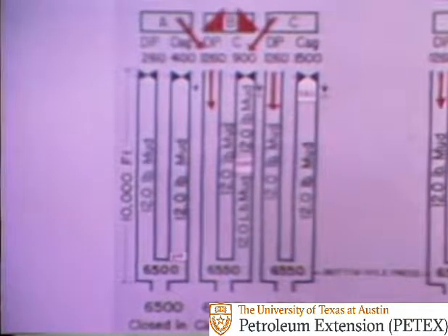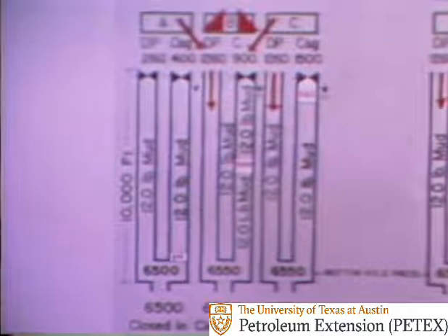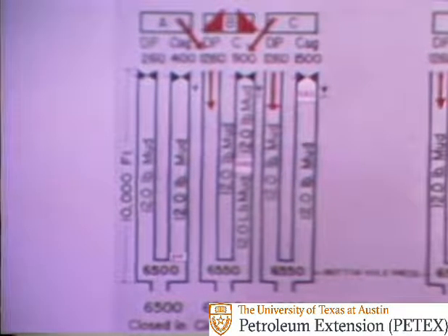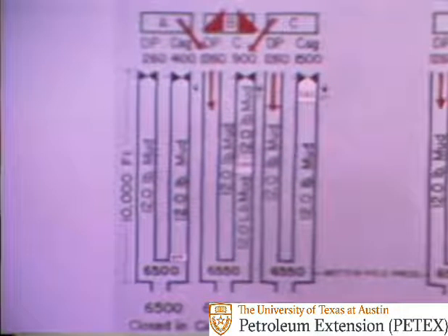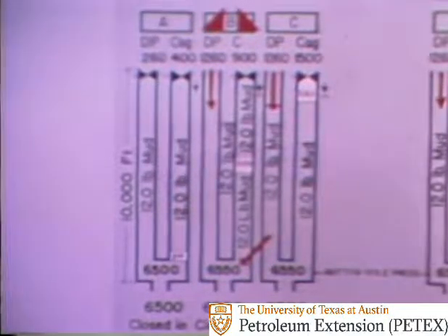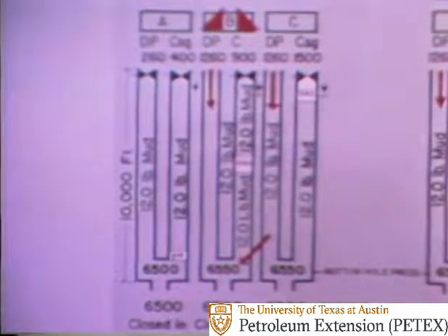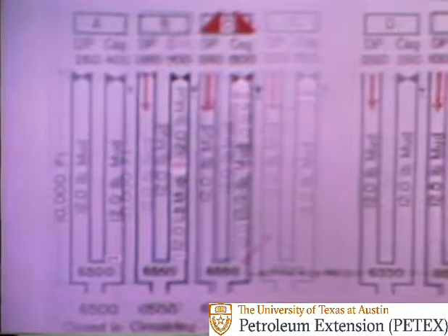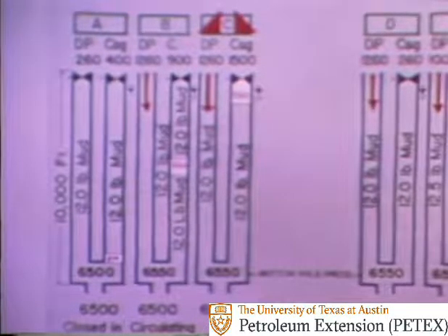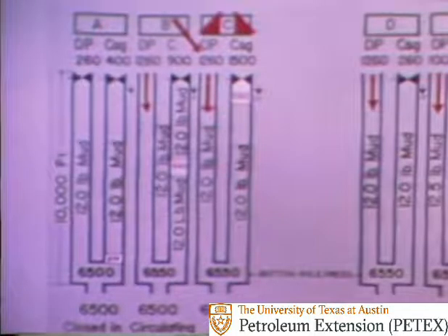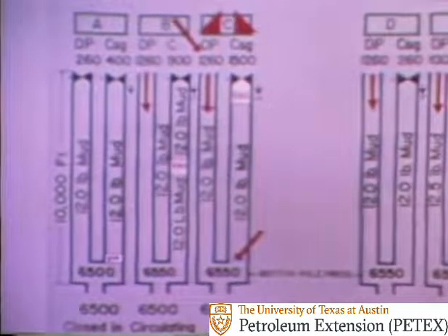The casing pressure will rise from the initial 400 psi shut-in pressure to about 900 psi when the kick is pumped about halfway up the annulus. The 50 psi increase in the bottom hole pressure is the amount of reduced circulating pressure required to overcome the friction in the annulus. As pumping continues, the choke is continually adjusted to keep the 1,260 psi on the drill pipe, thus keeping the bottom hole pressure constant.